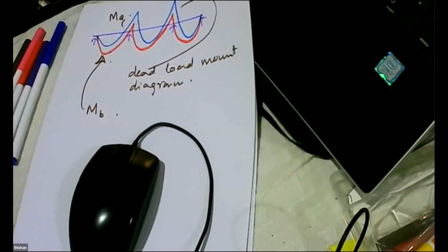Also, how about substructure design? I can show you how to do the computer modeling of substructure design as well. That would be great, sir. Yes, I can show you how to model the piles with Winkler springs, and if it is a raft foundation, how we can model the raft when the soil is laterite, when the water table is high, and when the water table is low.